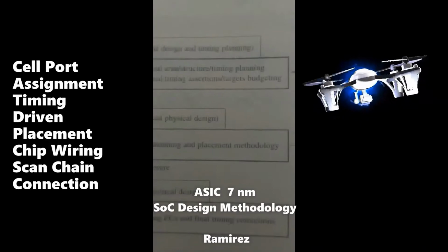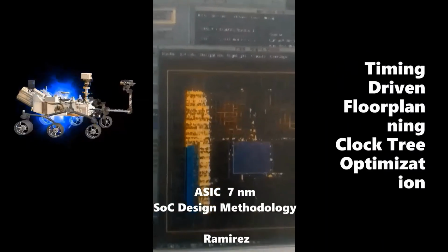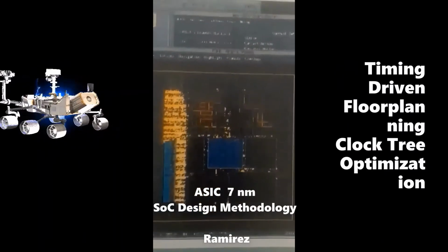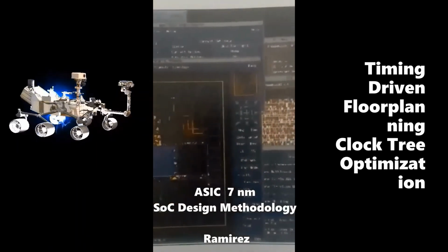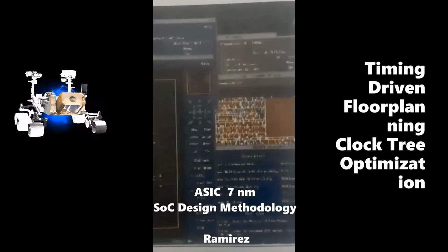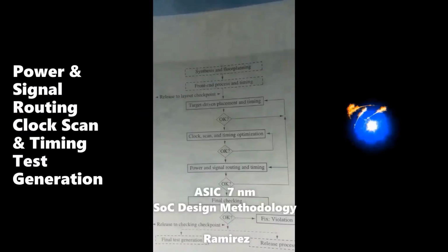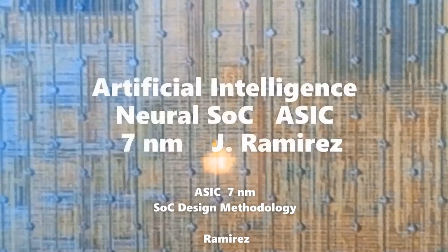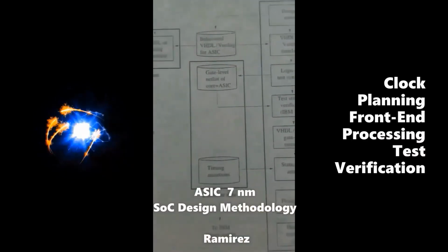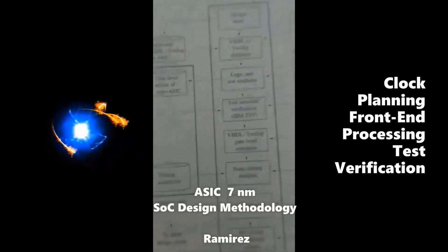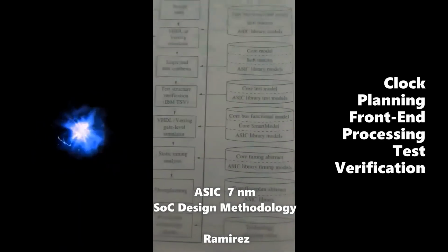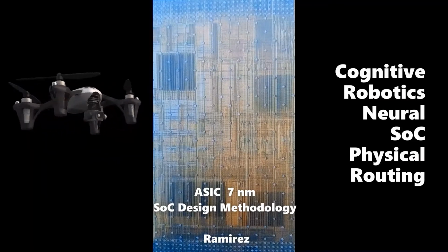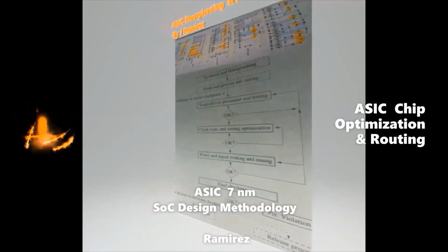Second, generate constraints for placement on the basis of a timing analysis done using idealized clock arrival times, add latches and estimates of wire load and RC delay before the physical design. These constraints include limits on the capacitance of selected nets and limits on the resistance of RC delay for selected connections.